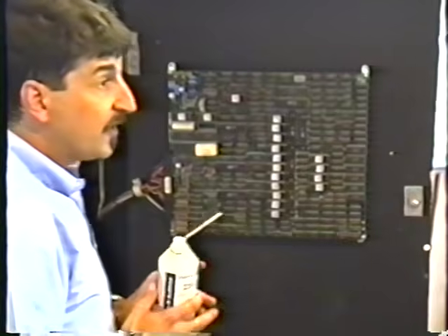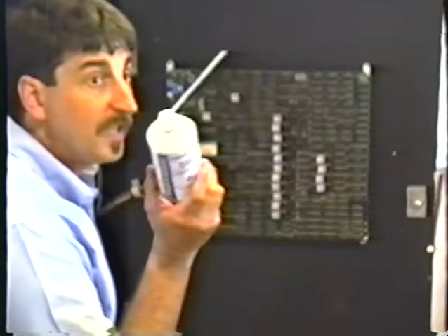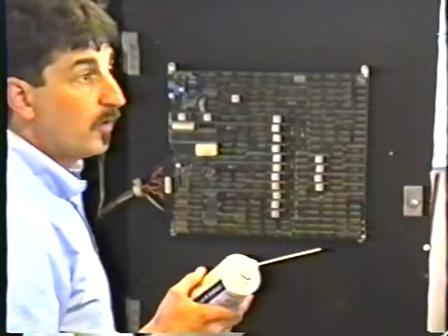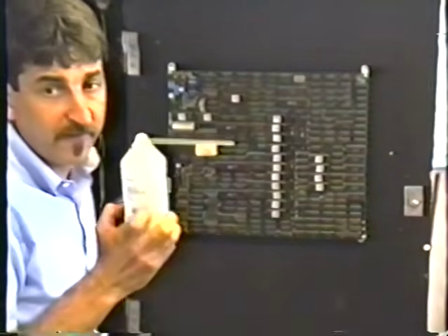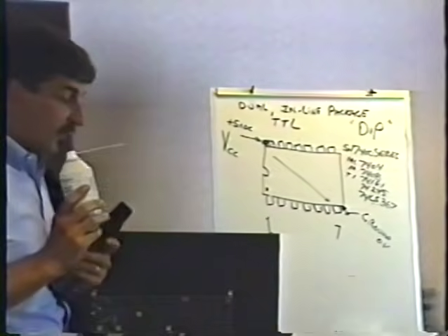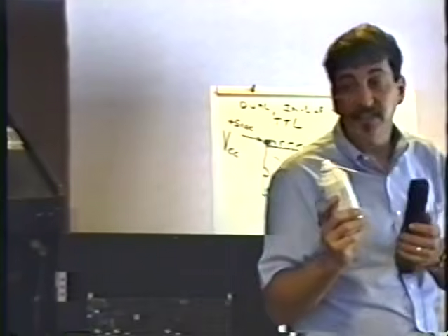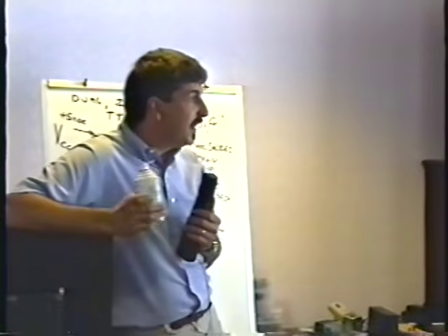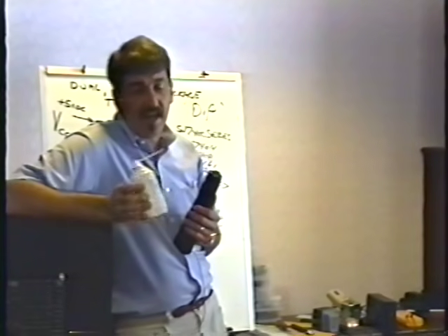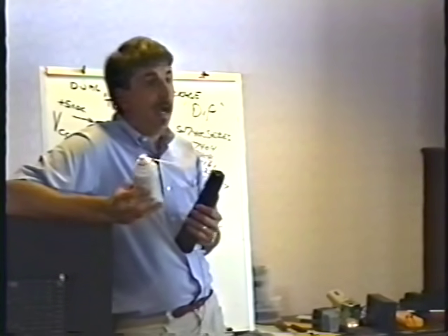Once you've located the chip, of course, this doesn't fix it. It only locates it for you. You know which chip is bad, same deal, then you order another chip. I have never failed to find a thermally intermittent problem with freeze mist. Never. I've gone through a couple of cans of it sometimes. It's always, of course, the last chip you hit. But I've gone through a couple of cans of it. You can get it at any electronics store.